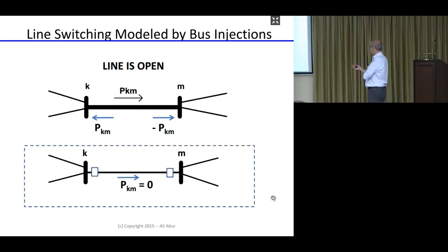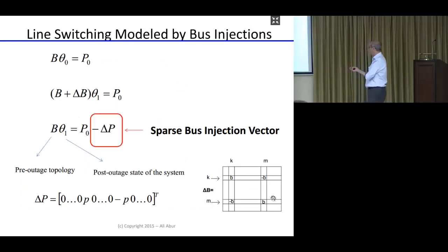So again, using this equivalence, what we are trying to figure out is this pair, and in the linearized version, since there are no losses, these will be identical except for their signs at the two ends of the outaged branch. So the problem looks something like this.